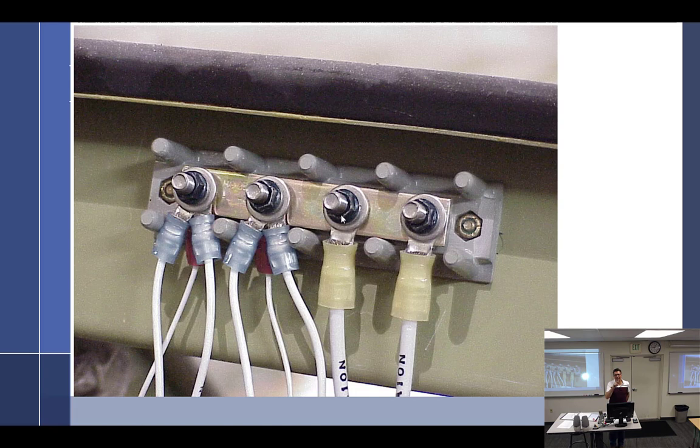What's on any given switch? We don't stack a lot of stuff on a switch. For example, if I have a radio master and I flip that on, and that's supposed to operate 5 different radios, then you make that go to a mini bus bar that looks like this, where each radio goes to it.